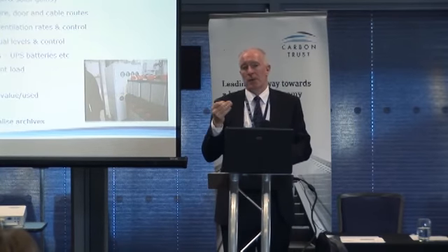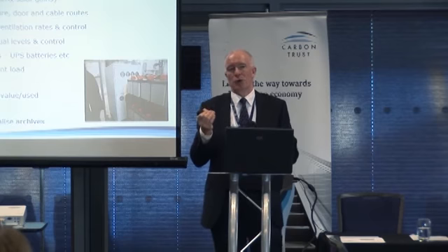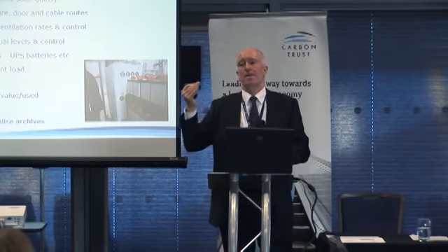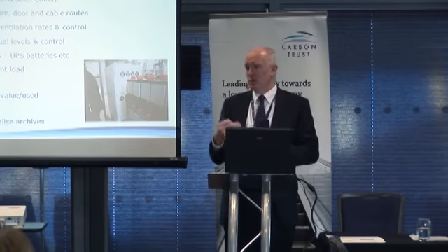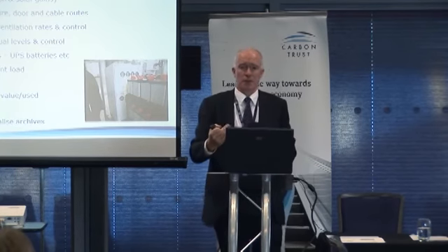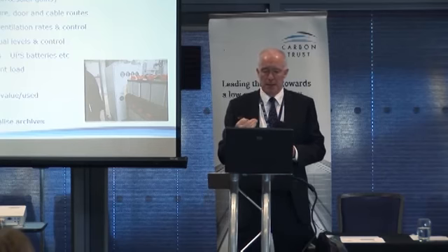Minimise your fresh air. There'll probably be a small amount of fresh air coming in for occupants, probably from outside. Minimise that as much as possible. Switch off the lighting. Make sure there's lighting control so that when people aren't there, the lighting goes off, and make sure it goes down to a minimum level.